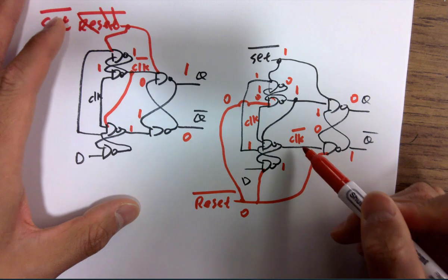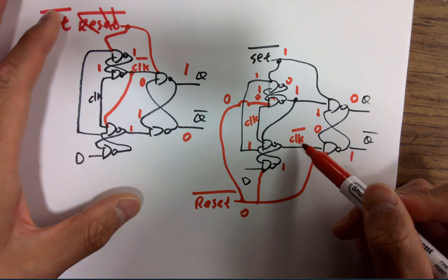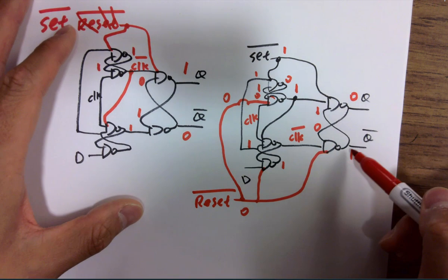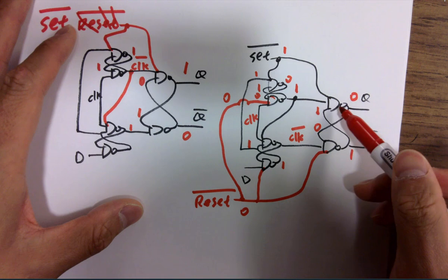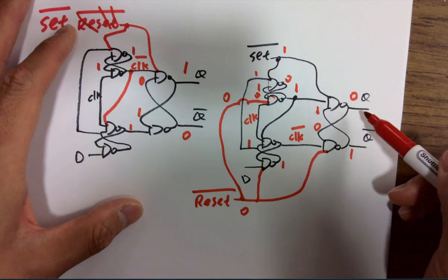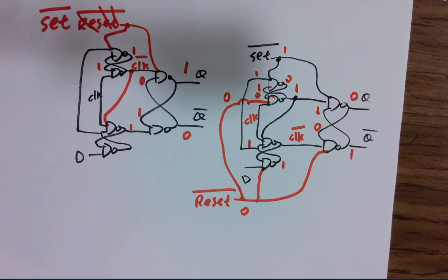1. Doesn't matter what that is, right? Clock not or something else doesn't really matter. So 0 will just kill this NAND gate. So 1 0 1 0 is stable, right? So Q is being reset in this case. Q is being reset.